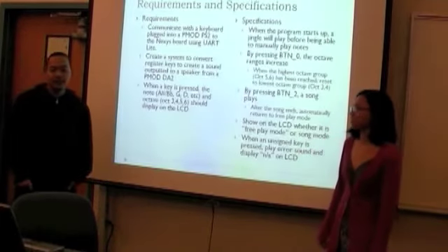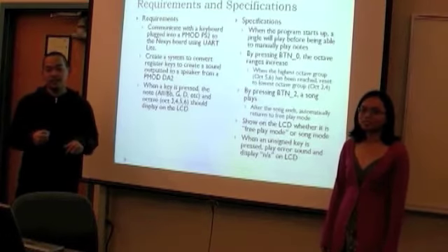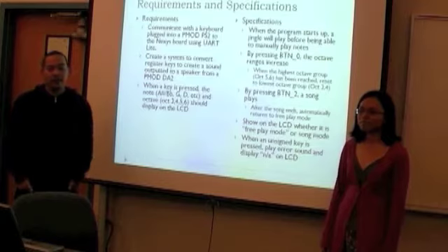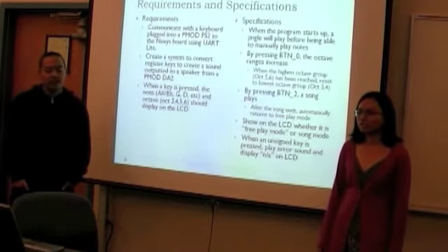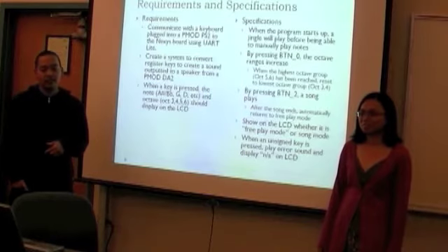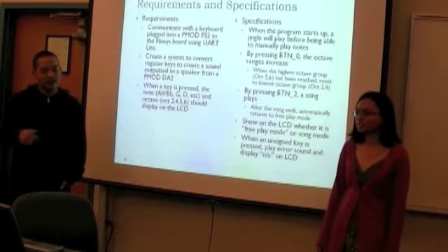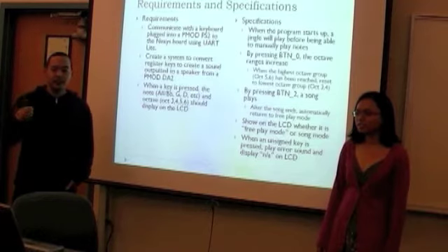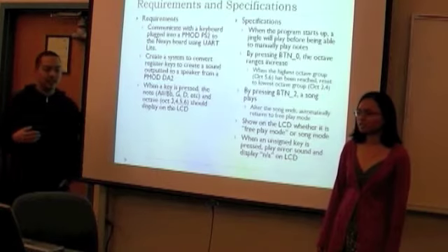So first, our requirements were to have the keyboard communicate with the Nexus board through the PMOD PS2 and the UART Lite. And then we wanted to take the scan code from the keyboard and convert it to keyboard notes. And also, our last requirement was when you press a key, it shows you the note is played, and if it's one of the black keys, it'll show the flat and the sharp, and also the octave of the note played.